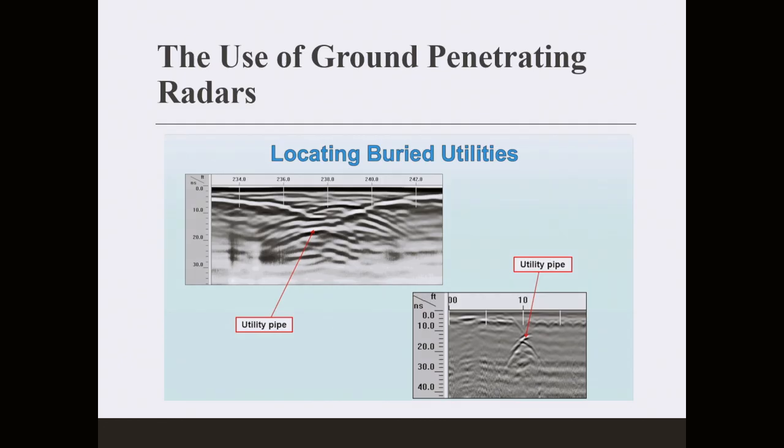We will see once we come to LiDARs, which is extensively used for asphalt. Most of the asphalt problems are superficial. You don't need penetration unless you are checking for bottom-up cracking. For bottom-up cracking, you'd use a GPR, but for anything top-down, like transverse cracks, alligator cracks, potholes or raveling, you don't need to go deeper. Investigating the surface will be more than enough, and for this we don't use GPRs. We use LiDARs, which is light-based, not sound-based waves.